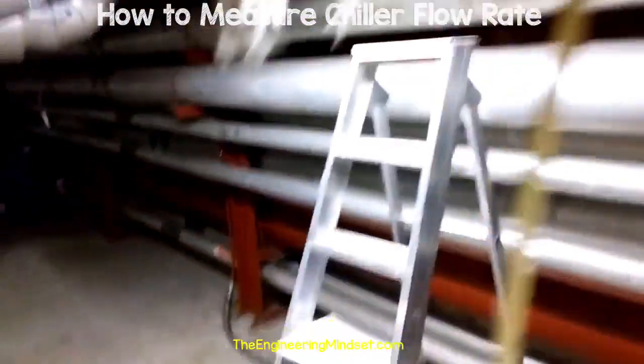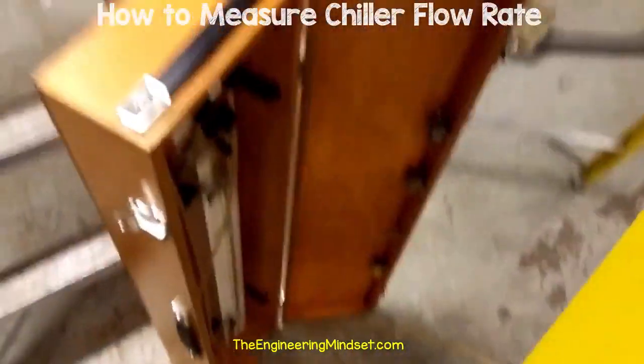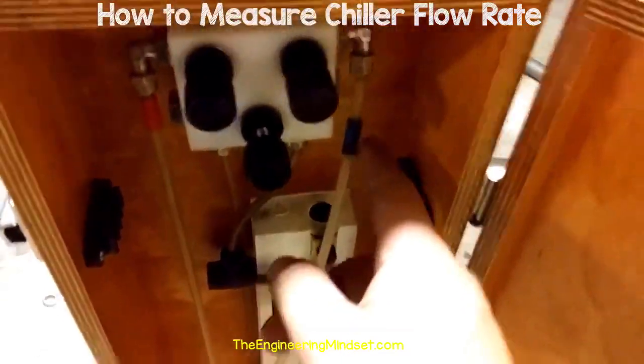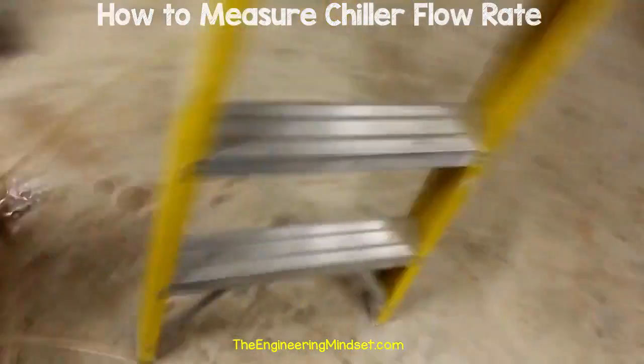You should also now check for any pockets of air within the hose or the manometer tubing and flush this out before continuing, as any air pockets will cause inaccuracies with your measurements. Then locate the blue low pressure hose and connect this to the blue low pressure side of the orifice plate.